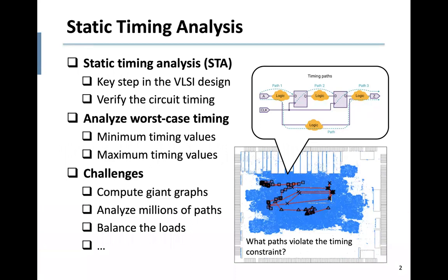Static timing analysis, or STA, is a very important step in the overall chip design flow. It is a key component in modern VLSI design because it verifies the expected timing of the circuit and ensures correct functionality after tape out. The term static means we do not consider the input vectors, the Boolean value of each pin, but the best case and the worst case delay and timing value of each node in a circuit network to analyze.